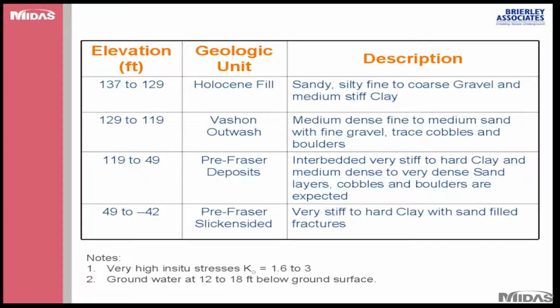If we're looking at these formations, the two main concerns are the existence of the cobbles and boulders at the site, and the very hard clay near the bottom of the shaft.